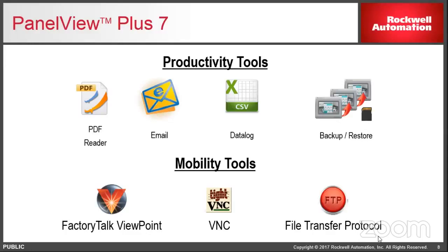And it's more of a mirroring situation, where what you see through the VNC connection is exactly what the operator sees. You can actually go in there and make changes on the screen if you need to, but you have to be careful with that. But so that's built in. So instead of having to walk all the way down to where the PanelView might be, once you have it set up and you have your security turned on and all that, you can get after it from your phone if you need to.